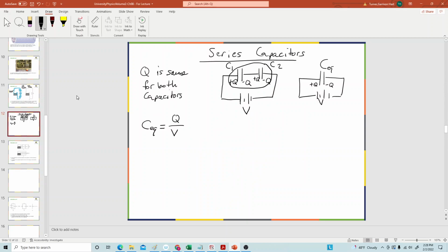And so, with farads being equivalent to a Coulomb per unit volt, whatever the value of my capacitors are, I can also apply the rule for capacitors to each individual capacitor themselves. Since voltage is a way to measure energy per unit charge, this is the total energy in the system, and that energy must be distributed between C1 and C2 with individual voltages V1 and V2.